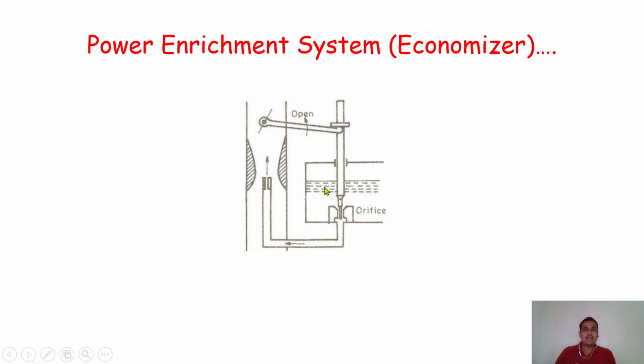Normally, the amount of fuel or petrol will be sent inside this particular tube, and then it will come out. In this case, sometimes the additional or required amount of air fuel mixture has to be sent. So one additional mechanical linkage is there. This is a kind of plunger, and this is a mechanical lever which is attached over here, and here is the choke valve. Suppose the air enters in this direction, and as the air pressure acts on this wall, this lever will get lifted up.